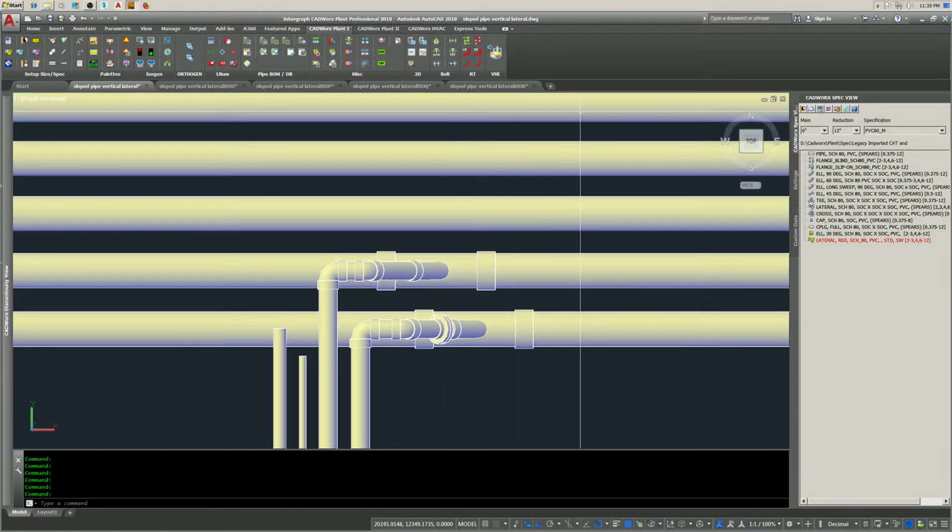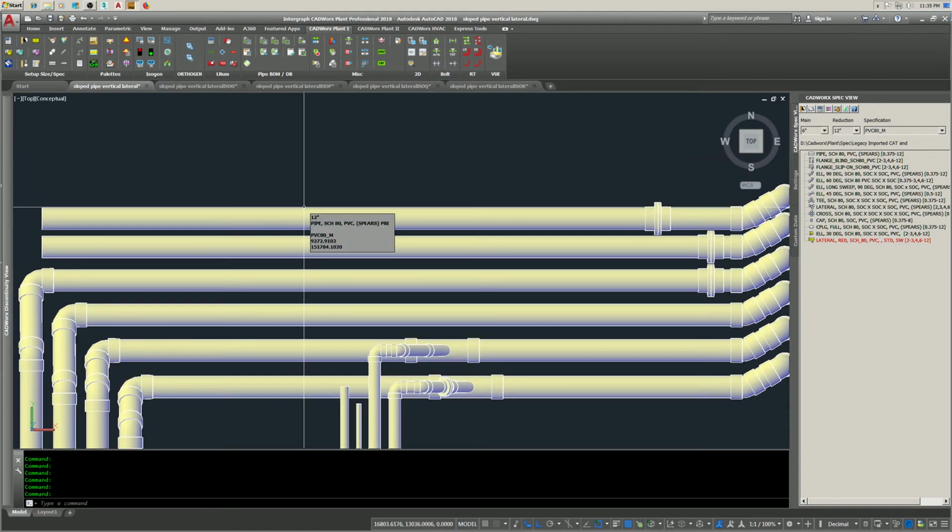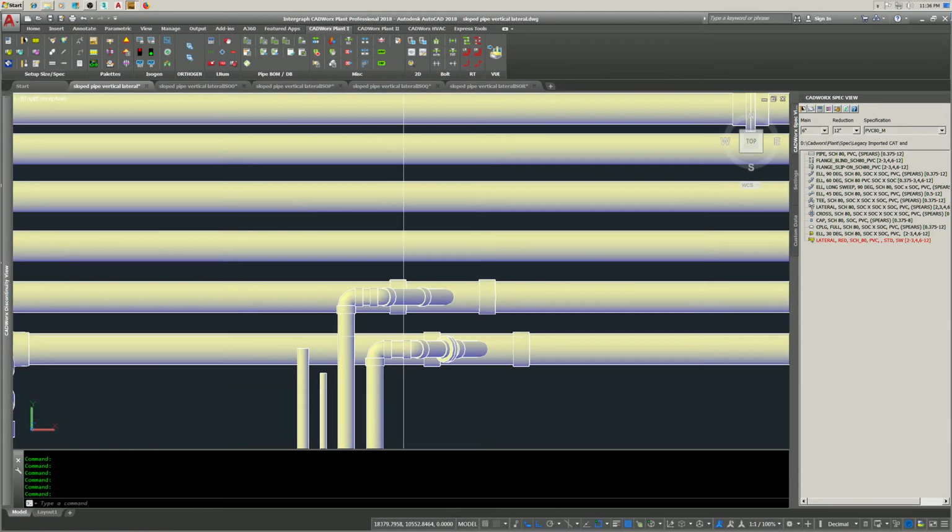You put your laterals in, put a flange and blind flange on it, and you're ready to go for future. Well, I hope that helped clear that up. This is the correct way to connect a sloped branch to a sloped main with a 45-degree lateral in the vertical rise.